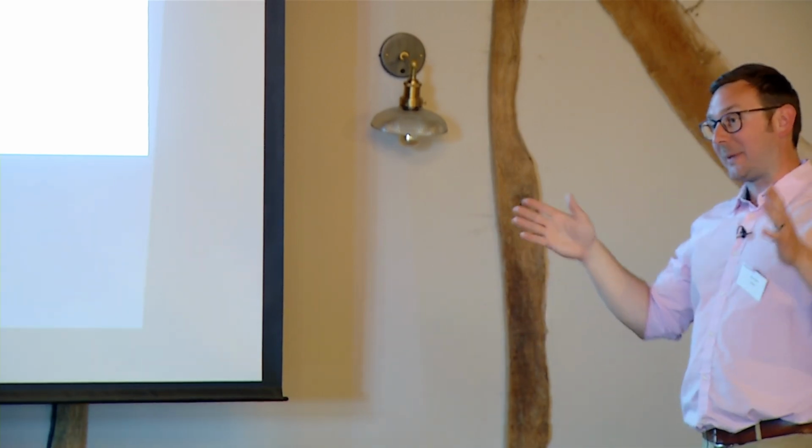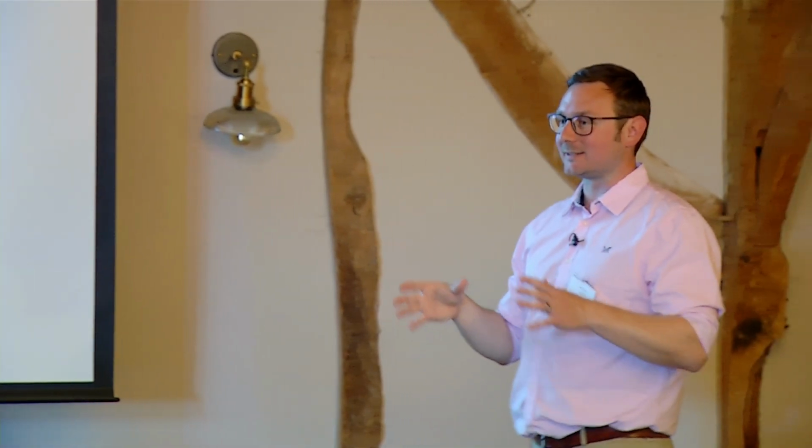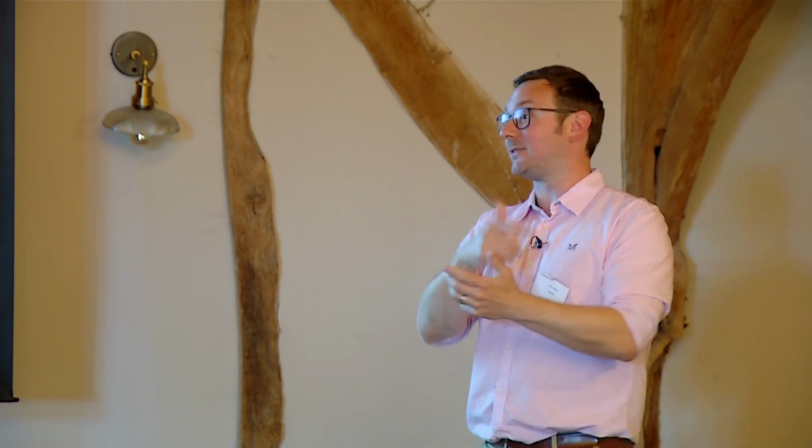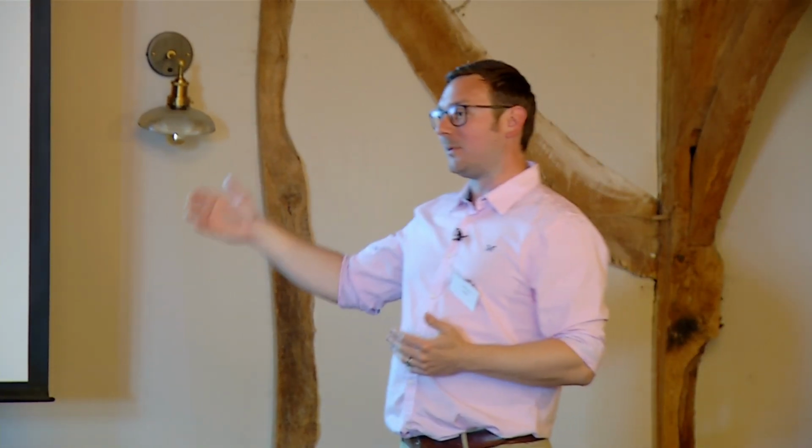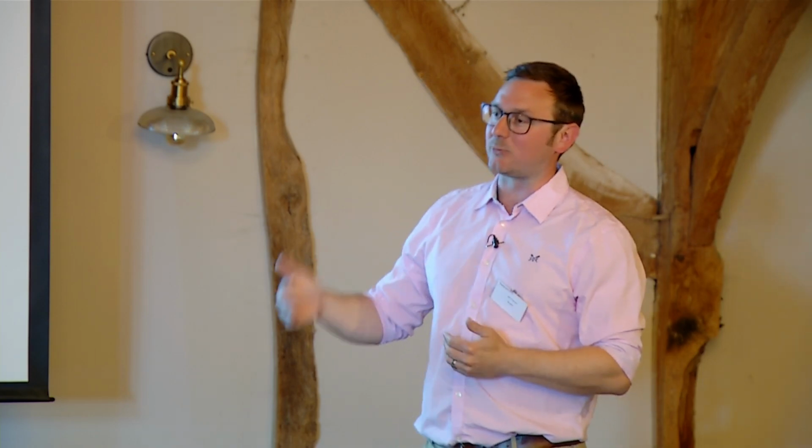So going back to the domestic instances, if you have a pair of semi-detached dwellings and the party wall is supported, for whatever reason, older properties tend to have it, by the roof structure, then yes, those roof elements, particularly if they pass through the wall, would need to have a fire resistance. If the party wall is independent of the roof, then no. I'll come on to B4, but what it means is boundary conditions.